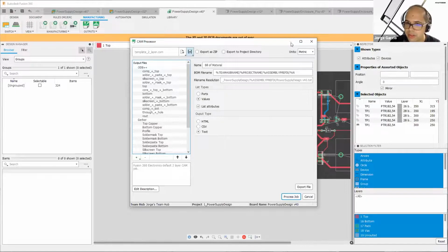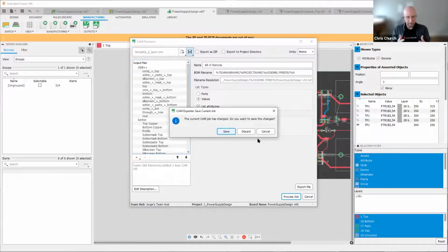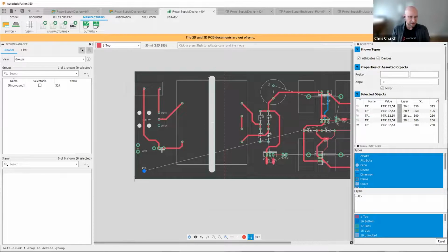Now, I know you guys take Gerbers, Chris, but is there any reason you would rather something else? Yeah, so Gerbers are perfectly possible, and we get a lot of designs that are Gerbers, bill of materials, and pick and place files. That does require a little bit more work on the user's part because sometimes these things don't line up perfectly with each other depending on how you export them, and we lose a little bit of knowledge about the design itself.